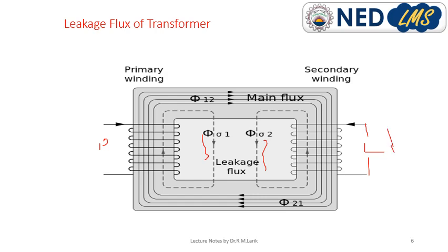A current will flow through that load, and that current produces its own magnetic field, which opposes the primary magnetic field from the supply, Lenz's law. So there are several paths of flux, but finally the flux will have only one path, that is the counterbalance, and one main flux revolves inside the transformer for transformer action.